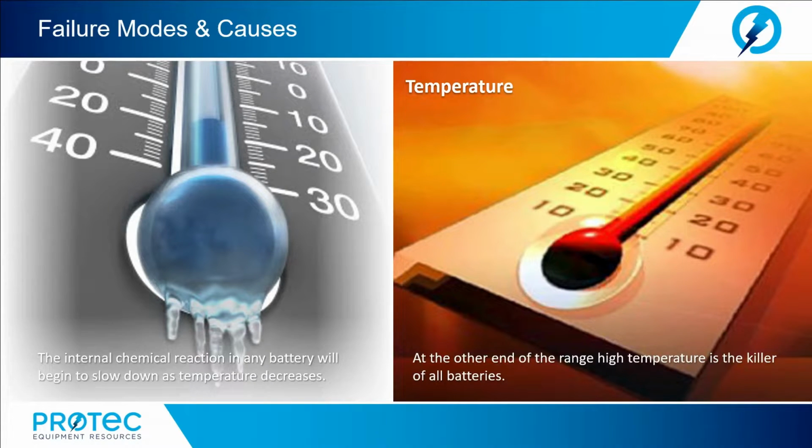Now, at the other end of the range, high temperature is the killer of all batteries. Once again, the degree will vary according to the battery technology. Lead acid at 95 degrees Fahrenheit will experience a 50% shortened life, while NiCad will experience a 16 to 18% shortened life. By applying what Swedish scientist Arrhenius learned regarding chemical reactions, we see that for every 18 degree Fahrenheit increase in battery temperature, the battery life is halved.